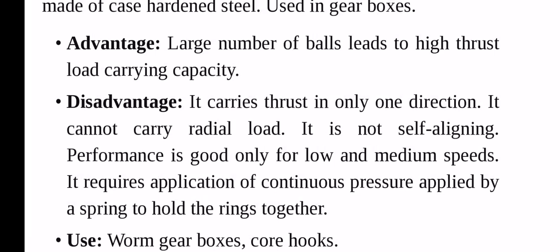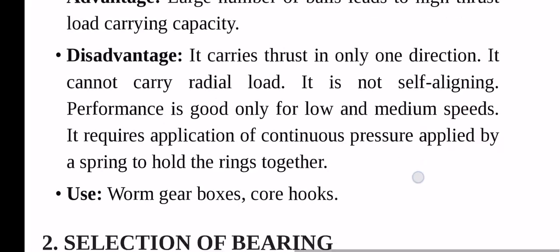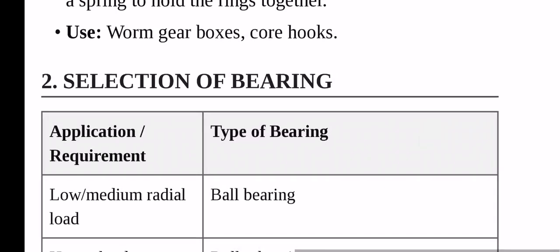It cannot carry radial load. It is not self aligning. Performance is good only for low and medium speeds. It requires application of continuous pressure applied by a spring to hold the rings together. Used in worm gearboxes, crane hooks.